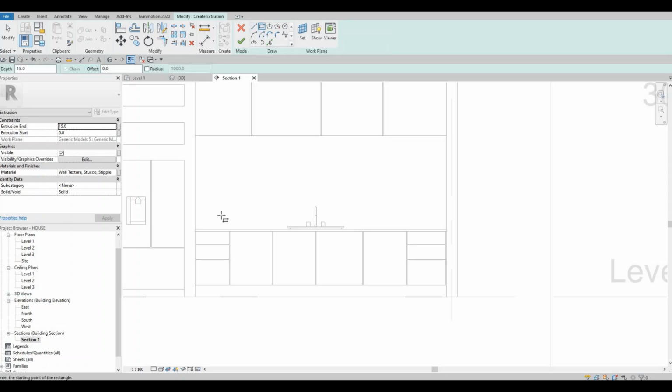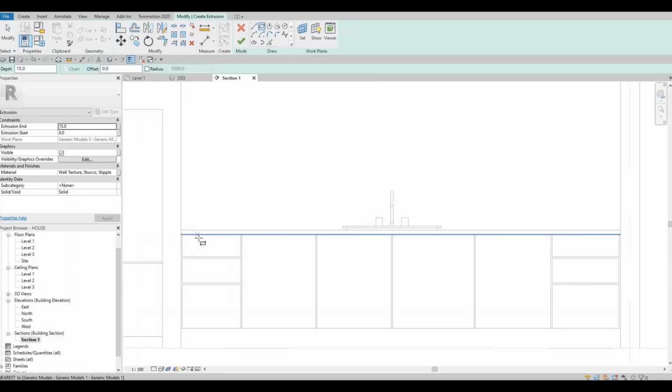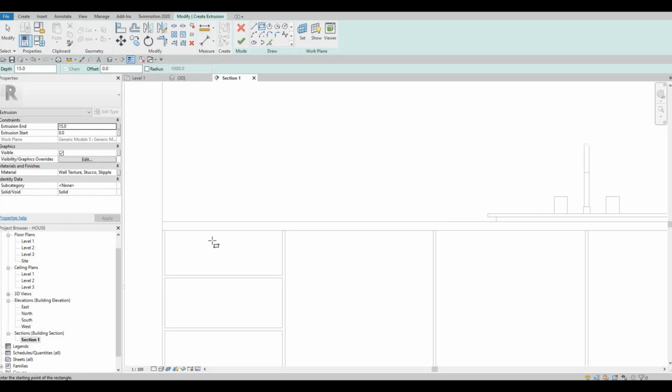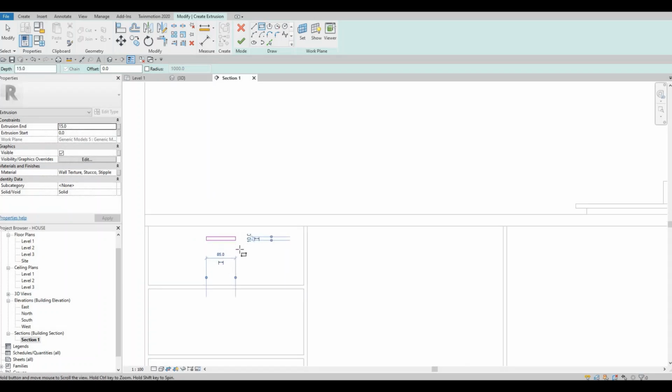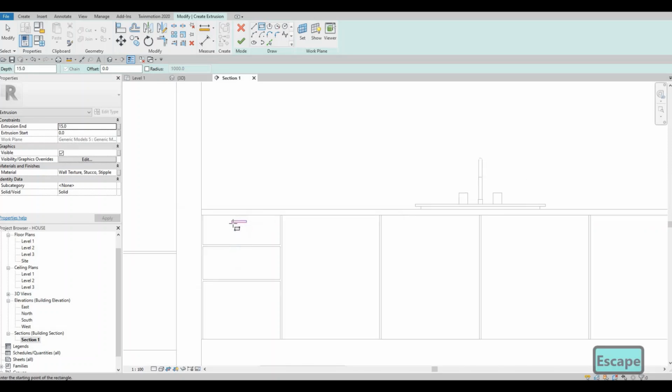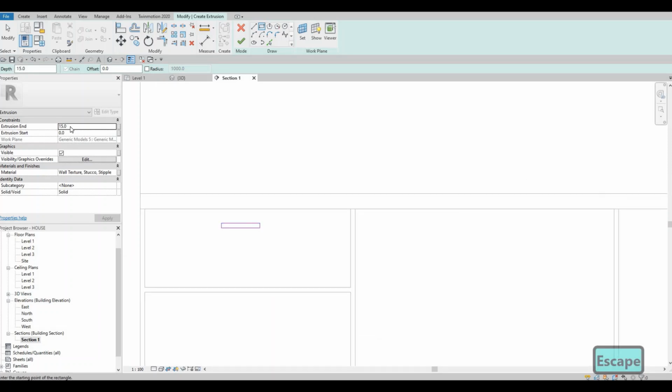And it will be a very simple rectangular handle. We're just gonna create this one, and then from here I'm gonna extrude it a little bit more, so around 25. So that's good enough.